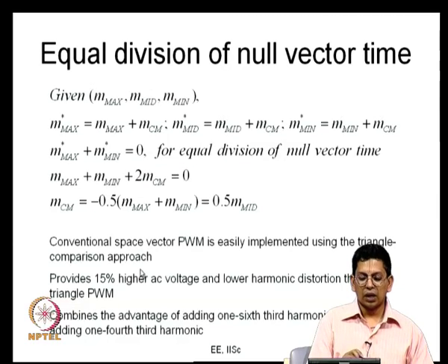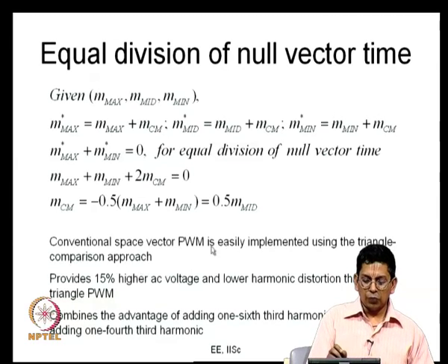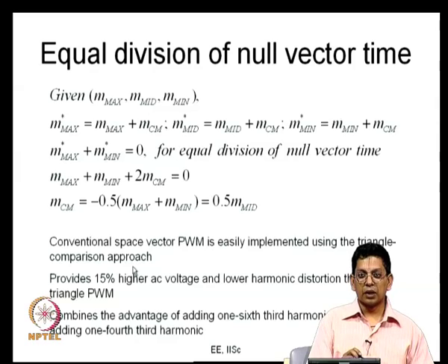And this is what I have said before, that if you want to implement conventional space vector PWM, rather than starting from the other end, that is you start with revolving voltage vector and sample, and then use the sample and calculate the times. If you have to calculate the times, sin 60 minus alpha and sin alpha are all needed. So, you typically need sine tables. So, the sine values of different angles from 0 degree to 60 degree need to be stored in a lookup table, etc. From that you have to do those calculations, and then you have to output the waveform.